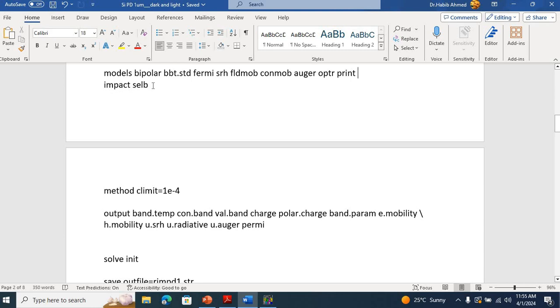Since there is an I layer in my structure and I'm operating it under reverse bias, if we are dealing with high reverse electric fields, then there could be impact ionization as well. So I've included an impact model for impact ionization, which is the Selberherr model.